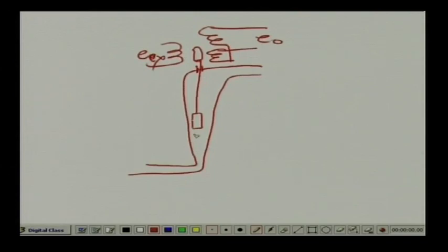If the bob, the float, moves, I will get a non-zero output voltage. It is quite obvious in the case of the rotameter that as the flow increases, the float will go up and up. This is another example of an LVDT.